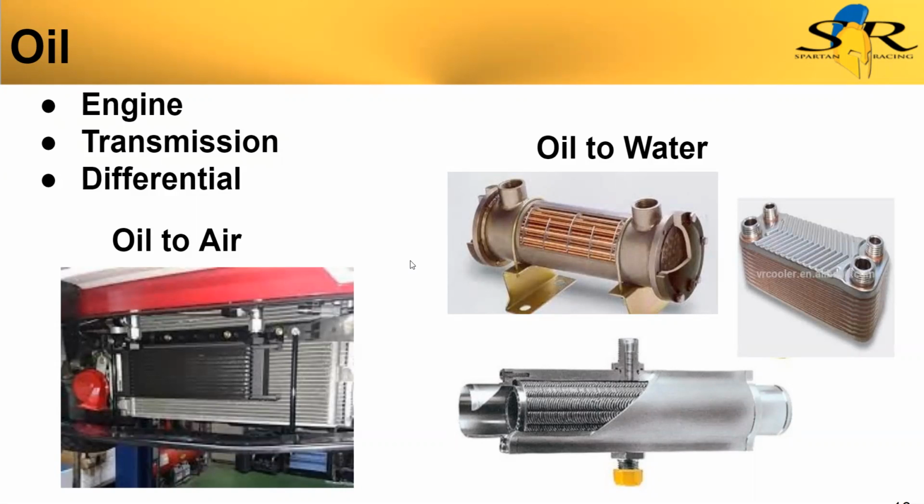That heat transfer is going to depend more on the pumping rate, how fast you can pump that oil or that water up to the front. And then also there's going to be a little more thermal resistance by putting that intermediate barrier of aluminum or copper in that heat exchanger between the oil and the water. So you're adding one more thermal resistance to the system, which would decrease the heat transfer rate. Does that make sense? Yes.